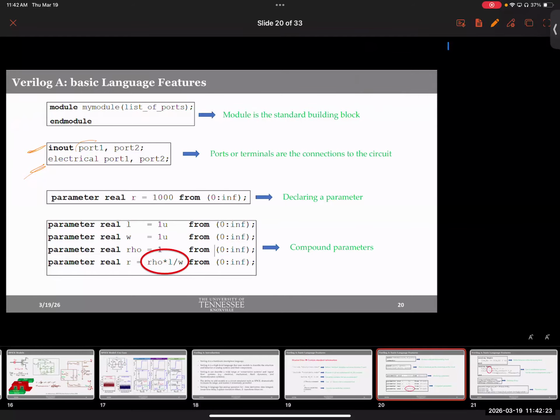First, you define your input and output ports. So these are inout, meaning this could be used as input or output, doesn't matter. Okay? And next, you are defining these ports as electrical. Notice, all of the ports that were inout are also mentioned as electrical. By the way, in what kind of situation can you deal with inout ports? Imagine you have a resistor, N1 and N2, two nodes. You can use either of them to provide a current, don't you think? So this node could be used as an input or as an output, by the way. You can take an output from that node as well.